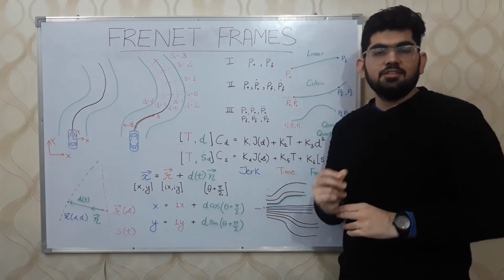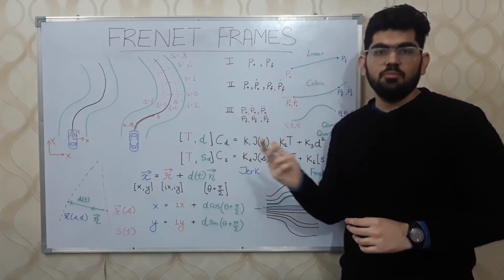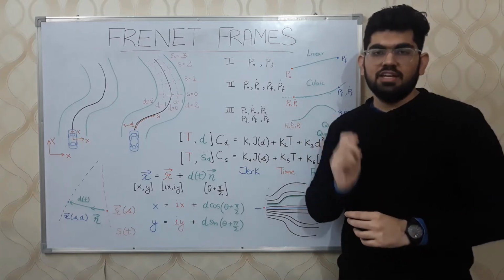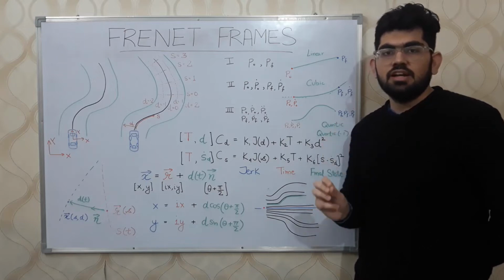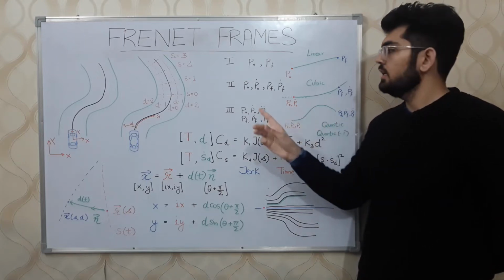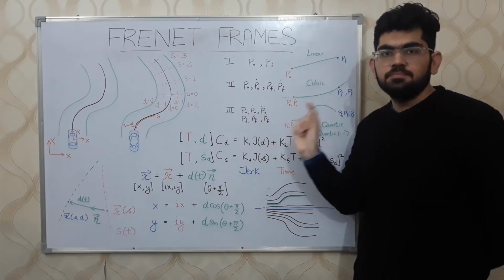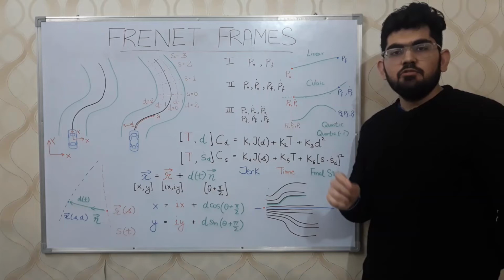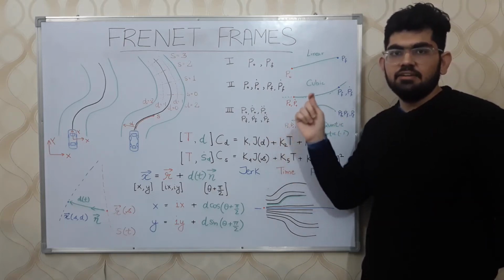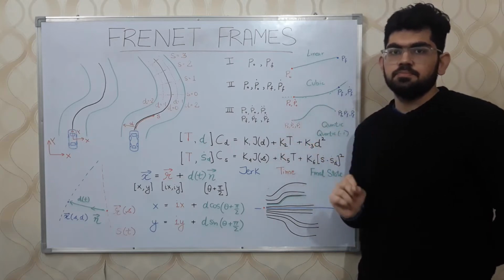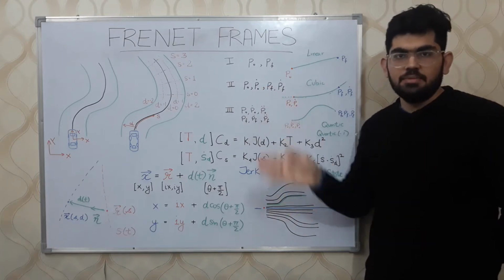Hence, any combination of these initial and final states can be solved using a corresponding polynomial which has an equal number of variables as the number of constraints. For the d-axis, we would already have the initial 3 conditions: d, the derivative of d, and the second derivative of d. For the final states, we want to ensure that the derivative of d is 0 and the second derivative of d is also 0.